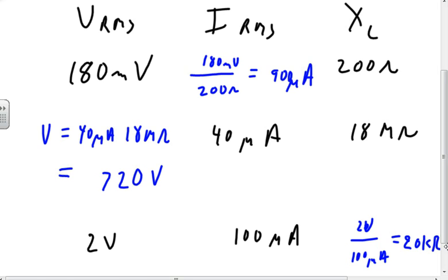All right, so 23 is next. Questions about that? So that's just V equals IR. Nothing changed. We have to use RMS voltages and RMS currents, because we're dealing with AC. So I couldn't say RMS voltage and peak-to-peak current and do a calculation for X of L. I'd have to change the values to RMS before I bothered to do something silly like that.